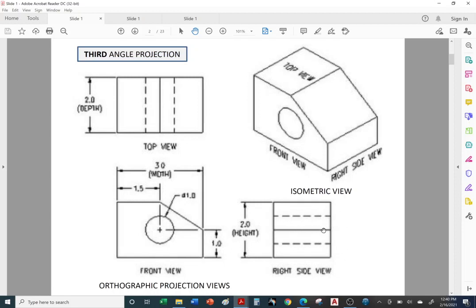Okay, so you can see this edge here, this object line or visible line. You can see it right there. This top line represents this line, and so on. Now, dashed lines are referred to as hidden lines. So what are these two hidden lines or dashed lines representing?